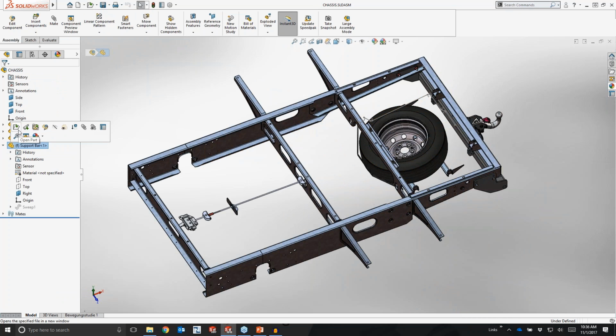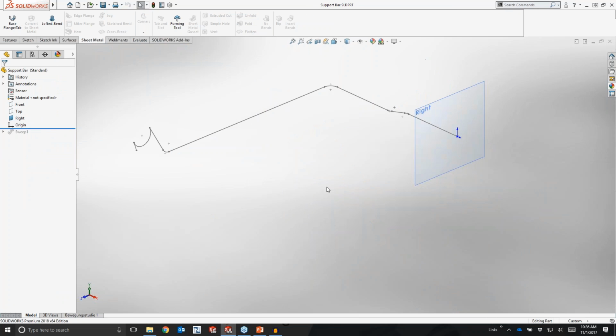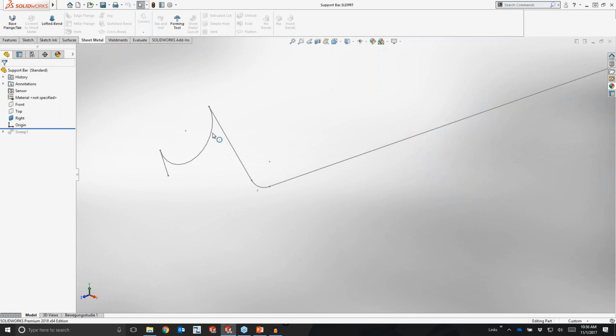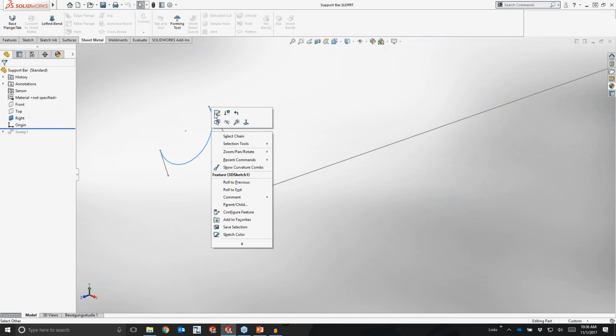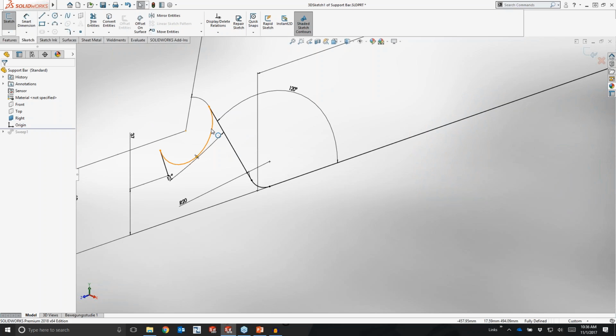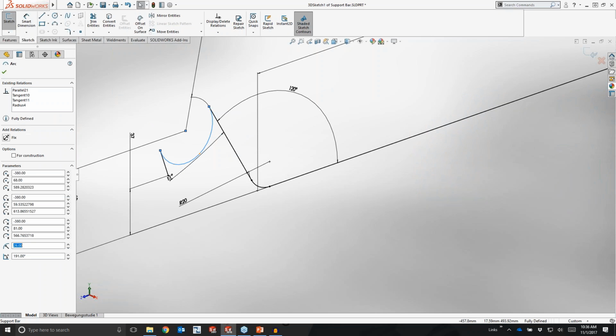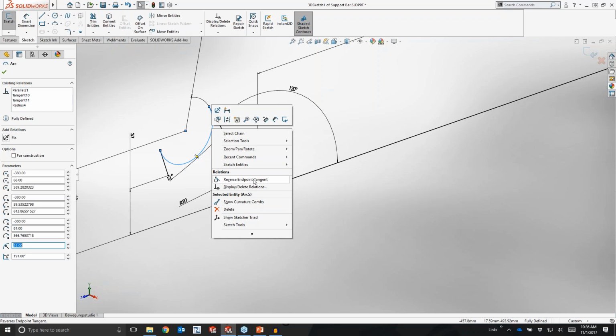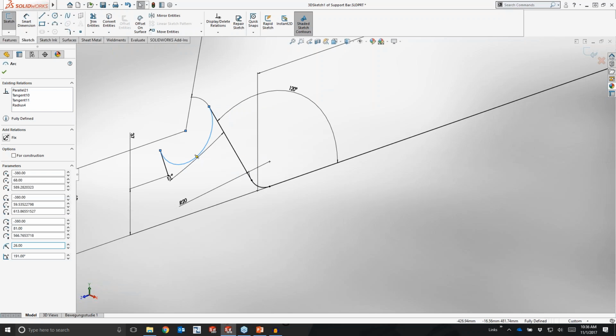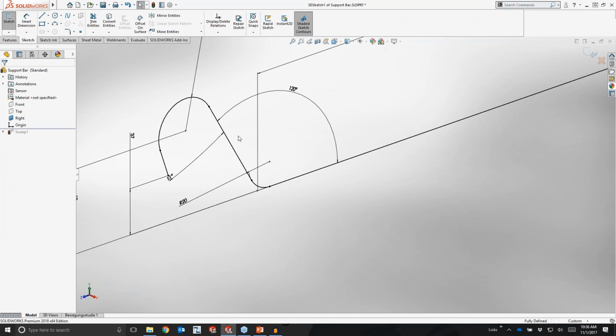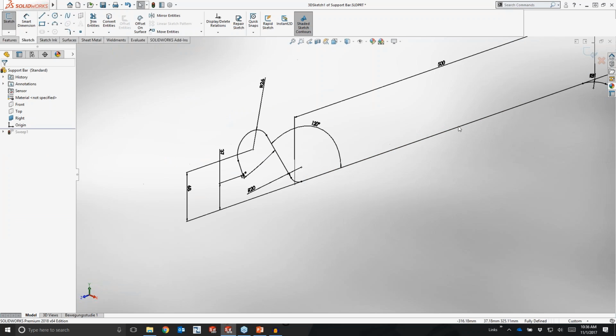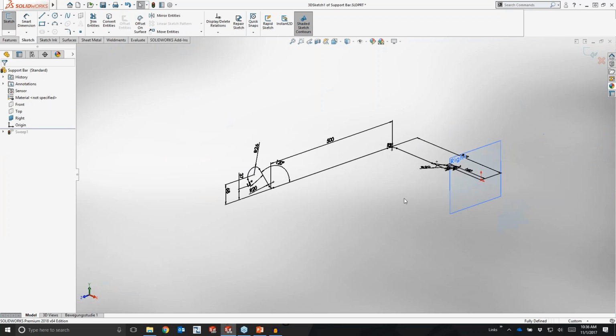I've got a part here that needs to be manufactured. It's actually going to be kind of a support bar for a spare tire. And it's going to be a sweep in 3D, and I've started my 3D sketch, but if you notice, my arc kind of flipped out on me. I made a change, and the sketch kind of flipped, and now I'm left with this problem. Well, with 2018, just reverse that endpoint tangency, and it's going to create a really nice look on that arc, meaning I don't have to go through and redraw that.